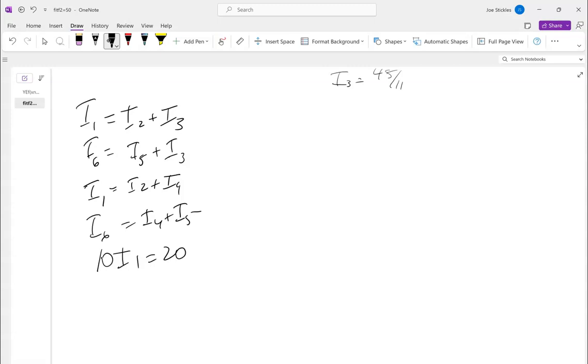This one doesn't really matter. I'll go around counterclockwise again, just because I went around counterclockwise with the other one. Just for argument's sake. If I go counterclockwise, what voltage drops do you have? You got 20I3, and that's positive because we're going in that direction, right? And the other one's going to be 10I4. So we'll add those two together. 20I3, and I'll switch back over to the screen here in a second where I'm writing these down. 20I3 plus 10I4. We're going in the right direction.